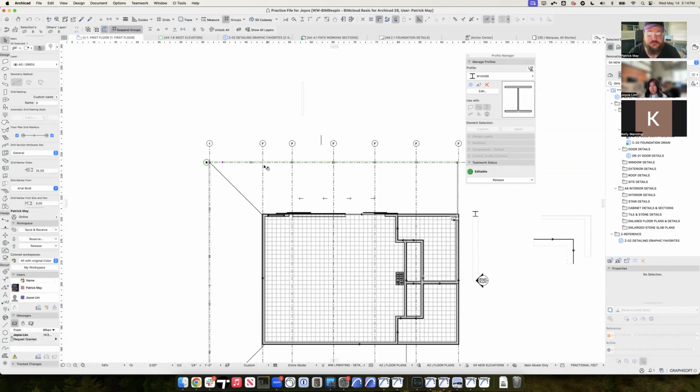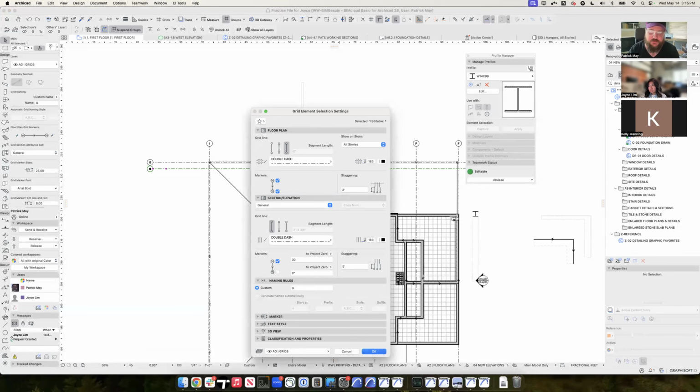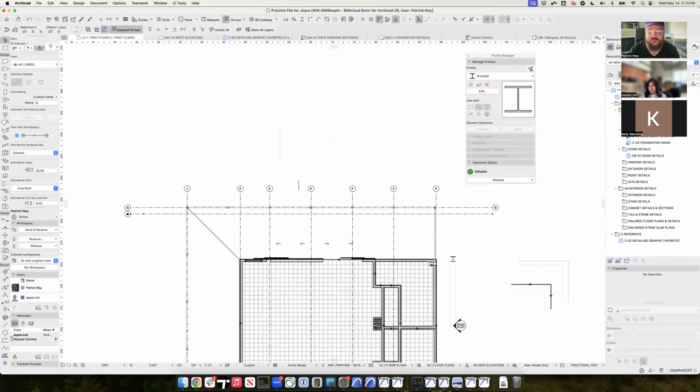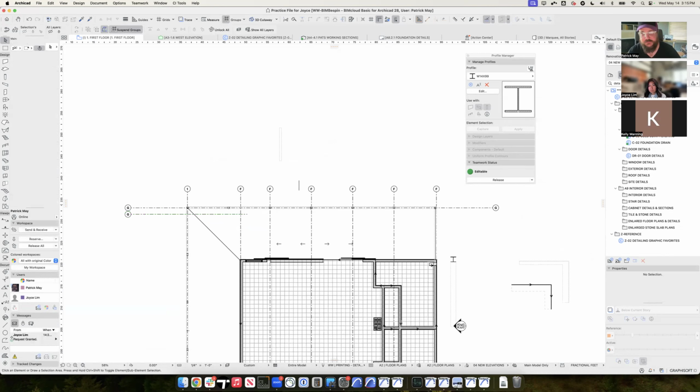If you do end up with grids that are kind of close together for some reason, let's say they're like 18 inches apart, you can actually offset them out in plan view. That's not very common. It might be common if we have a grid on just one side. So you can actually turn the grid off on one side so it's not running all the way through. So maybe you've got grid 1 and 2 on this side and then it jumps down to 3 here. But let's go and drop a grid there.